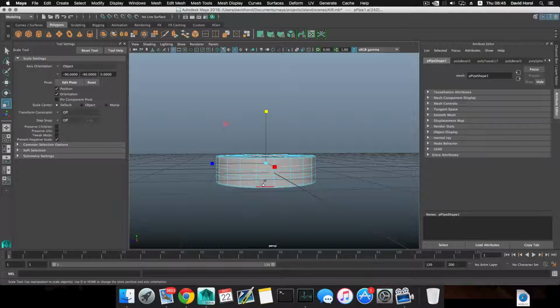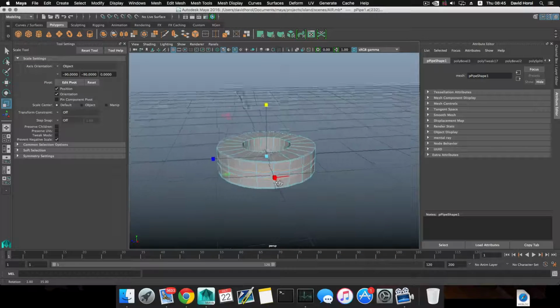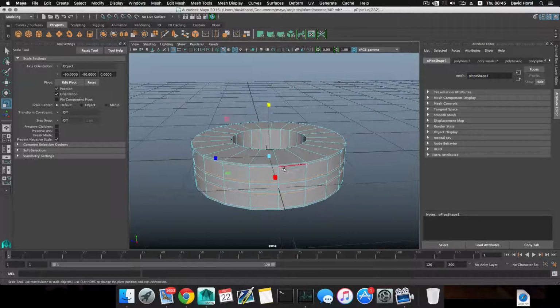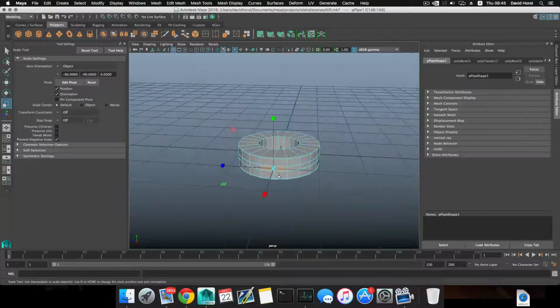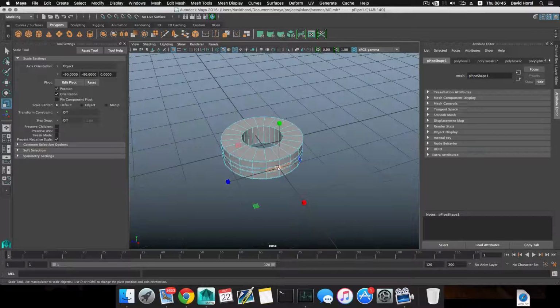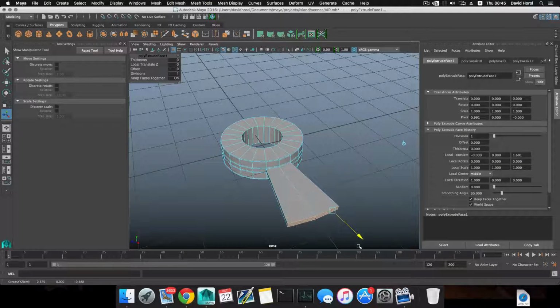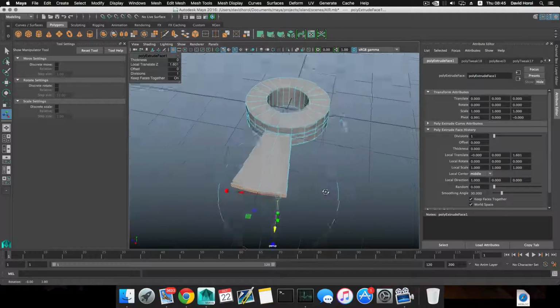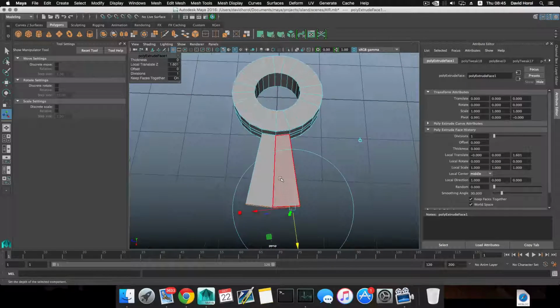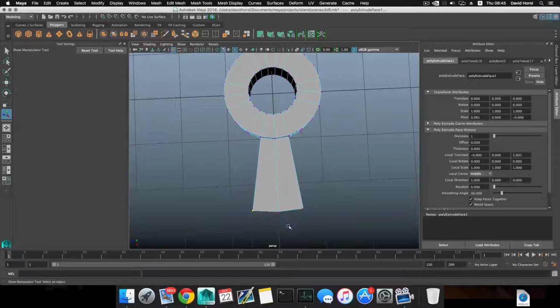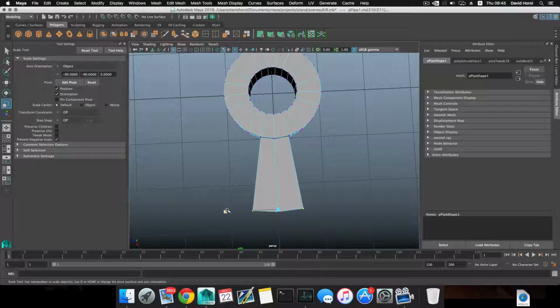So now that I know where I want those, I will bring those near. Okay, that way we can grab these two. It doesn't matter which two, we have 21 and it's set correctly, so we can grab these two, extrude them, move them over here. Okay, then we can right click, choose vertices. We can grab these two vertices.